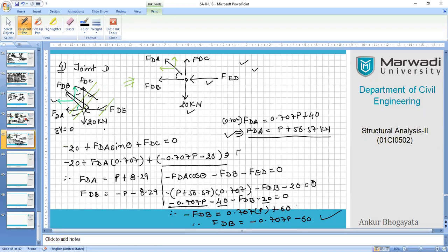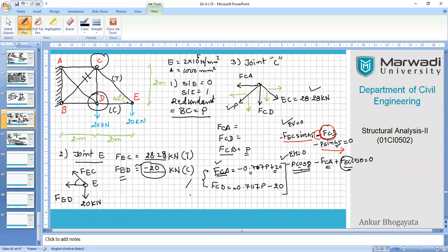So now largely we have worked out all the member forces. And please remember that the AB member is not in the picture because it's a part of the wall system. So it is largely considered as a member which is already without any force. So let's write down all the other members in a list, like how many we have, nearly 7, right?